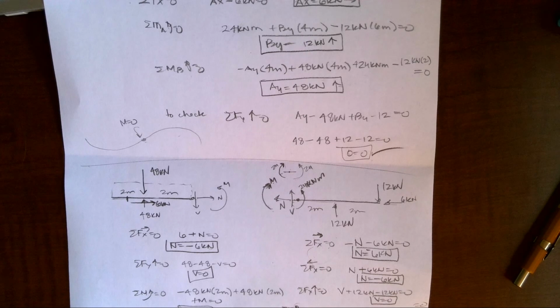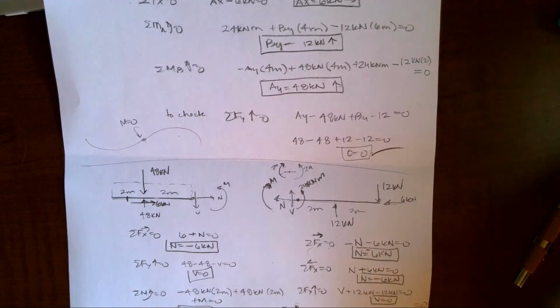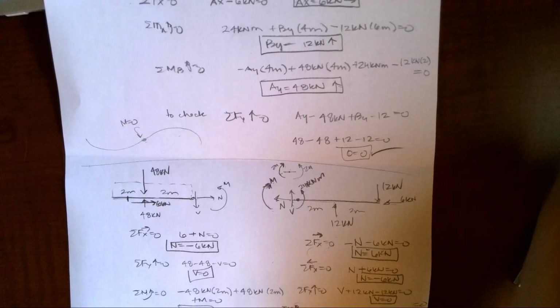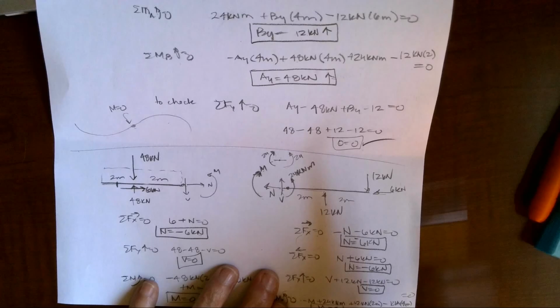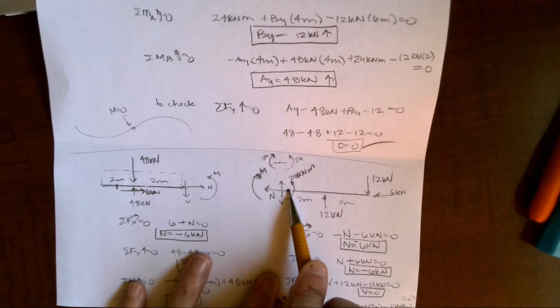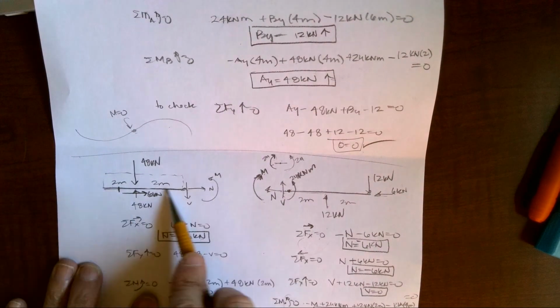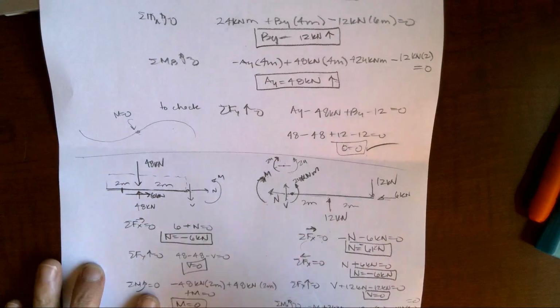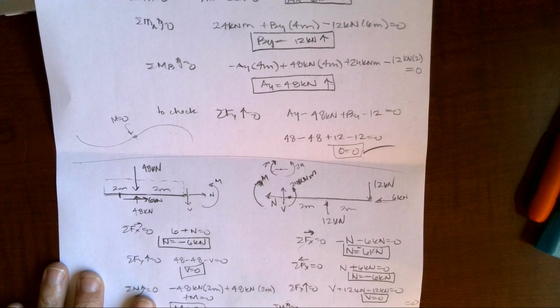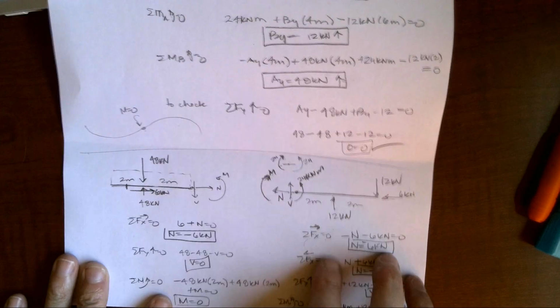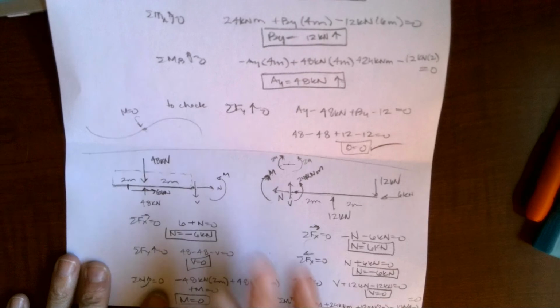My next videos that will be coming up are going to be finding internal shear and moment equations. Right now we've just been looking at a point in space where we're finding internals, but really I need to know all the way down the length of the beam what my shear and moment looks like, because that's how I'm going to be able to design for those maximum values of shear and moment, both positive and negative. So instead of trying to cut the beam into a million little pieces and do free bodies and equations over and over, I can actually draw a picture of my system. So that's up next. See you guys.